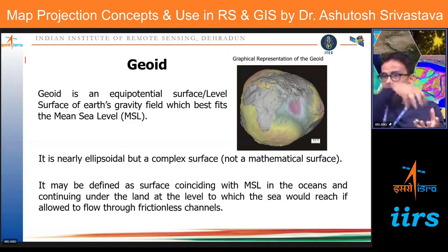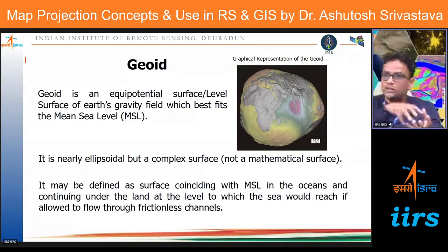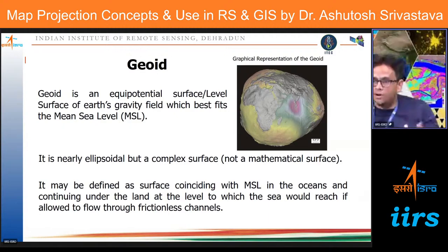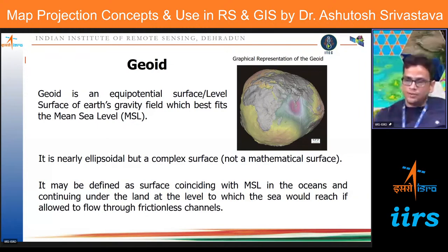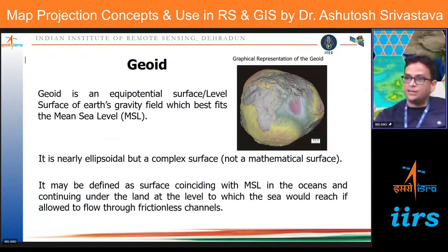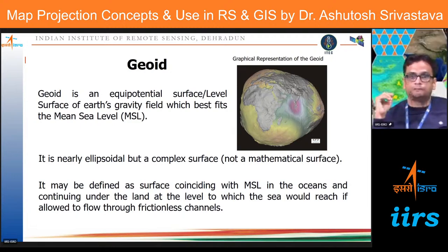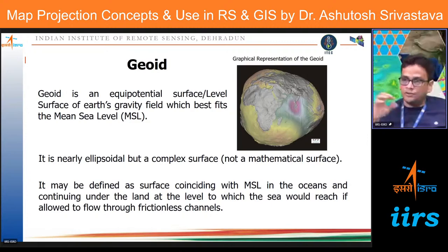From there, we attach information onto this ellipsoid and make it more real, like the Earth, and that is called a datum. So today we have WGS 84 and GRS 80, all geocentric ellipsoids or datums available. Now latitude and longitude we can derive on this datum or ellipsoid.